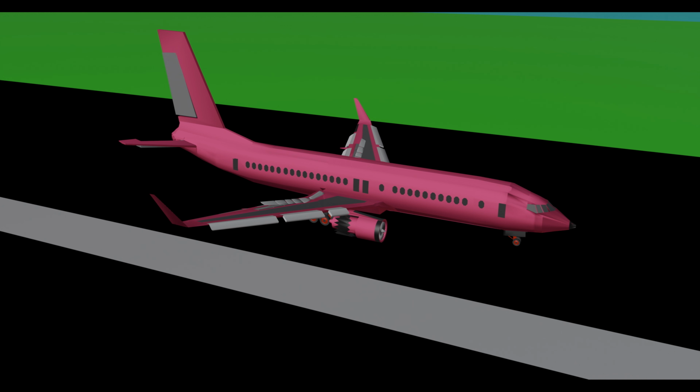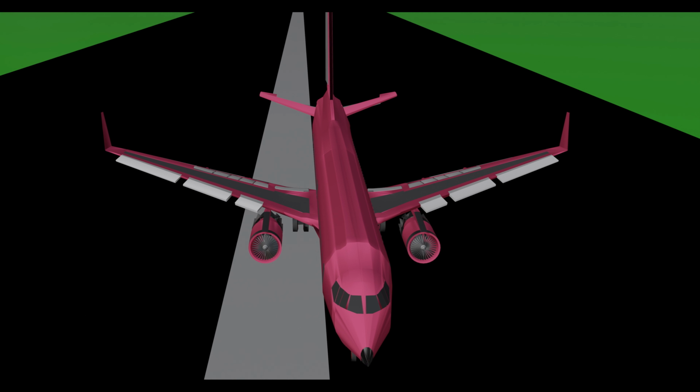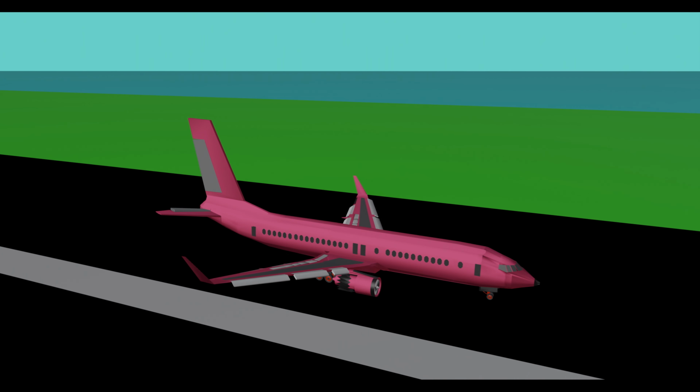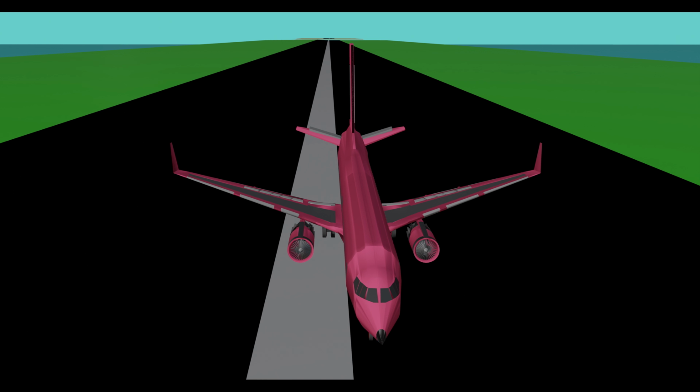Well, after the speed is decreased, the flaps and slats are set to normal position. Spoilers pivot down, reverse thrust is deactivated. The aircraft therefore goes back to normalcy. At this stage, the aircraft can proceed to parking.